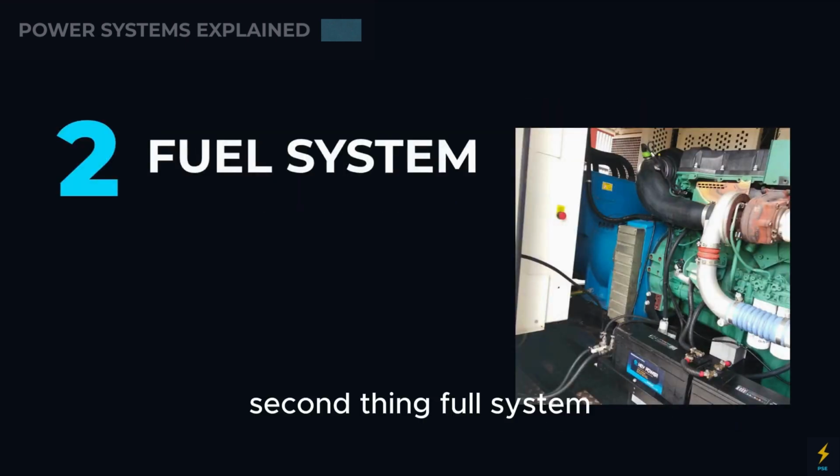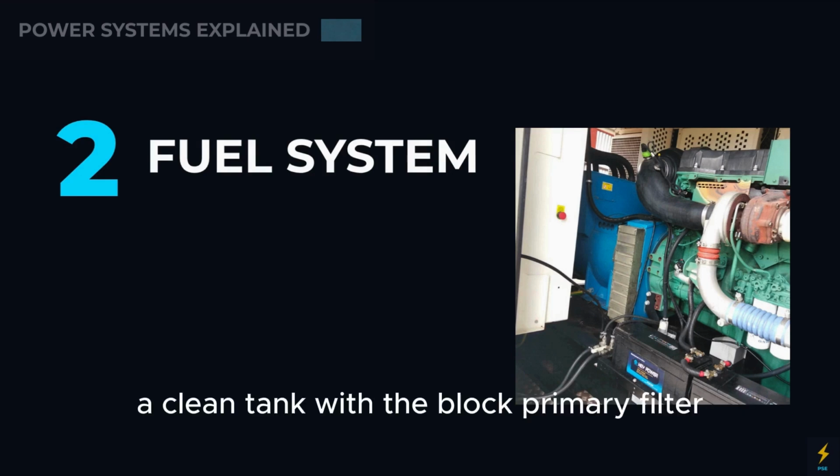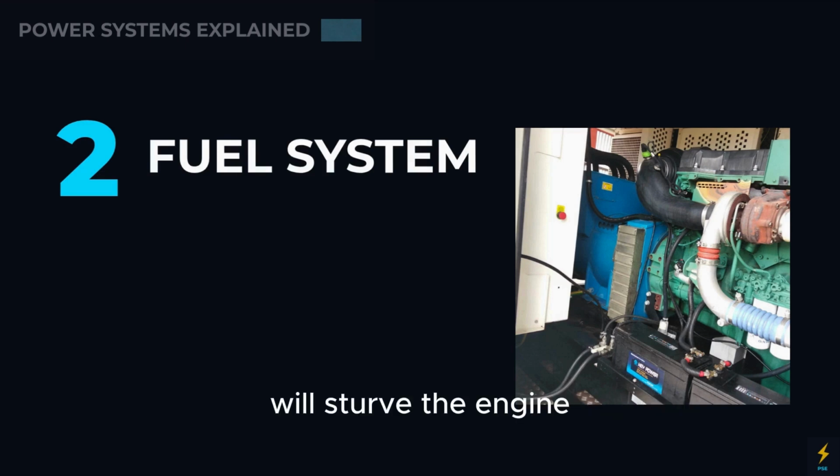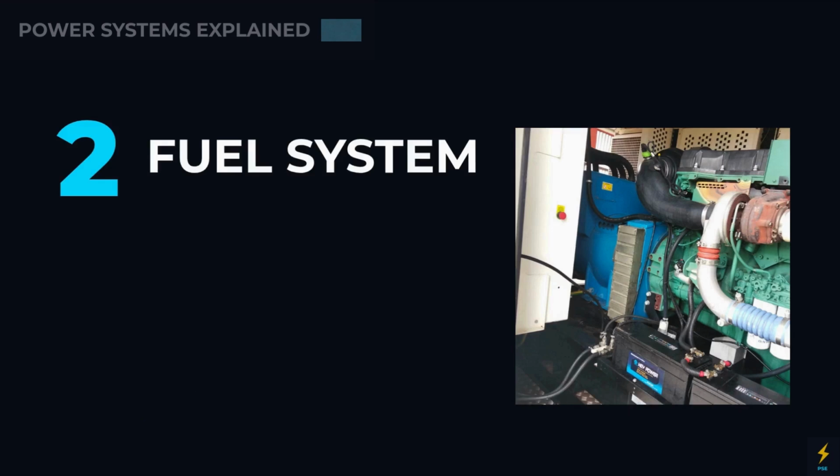Second thing, fuel system. I check fuel pressure and the injection pump inlet, not just at the tank. A clean tank with a blocked primary filter may starve the engine under high load even if it runs fine at light load.